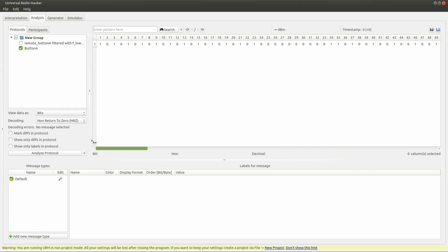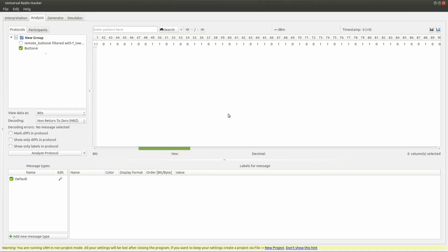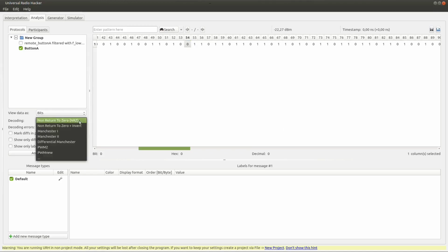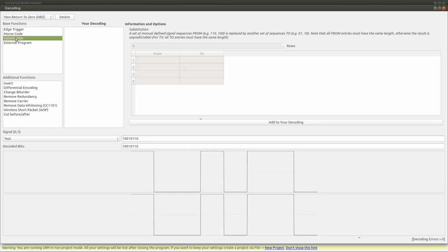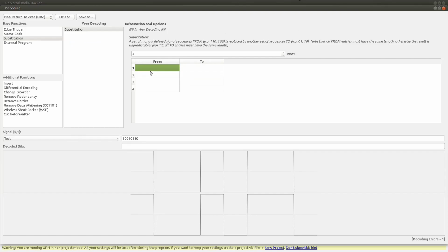So it's probably not encoded in RZ, because generally when you see something like that, some duty cycle and some other bits, sometimes you may be looking at some Manchester decoding. But just looking at the bits in here, it seems like there are only two values, like 100, 110, 1100. That means there's some sort of encoding called PWM. I have already done some PWM decoders, but I can also show you that this is pretty simple with URH, just to sell you URH.